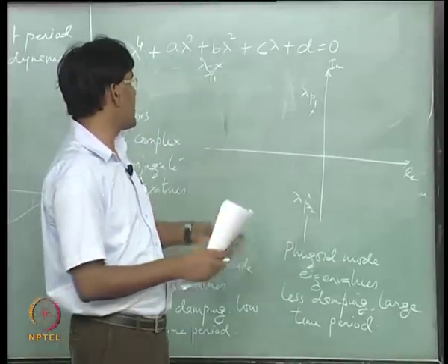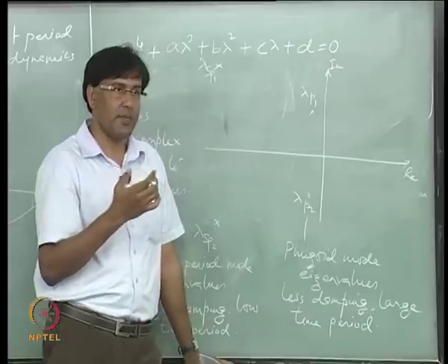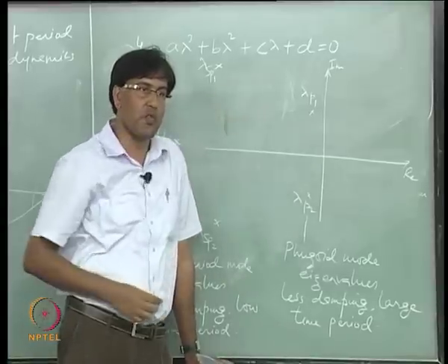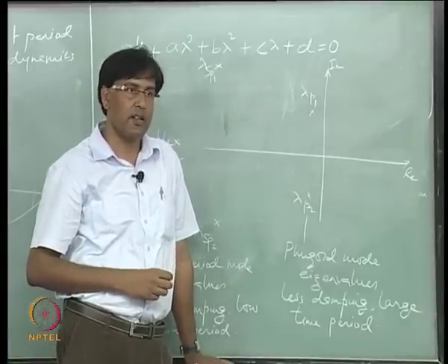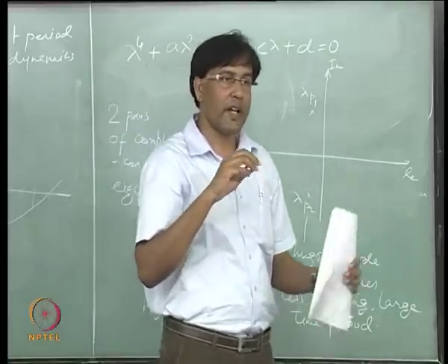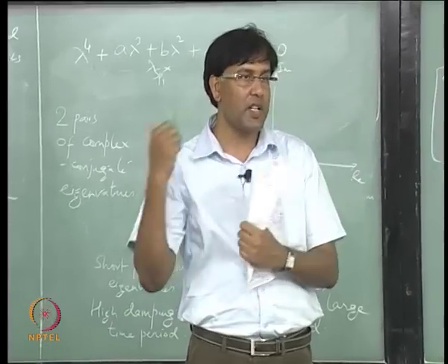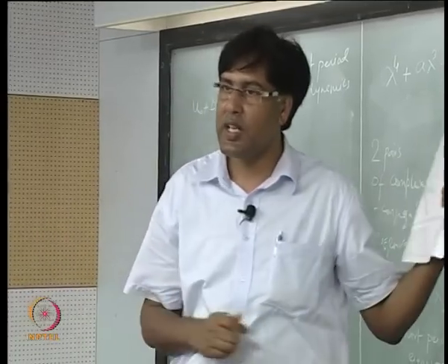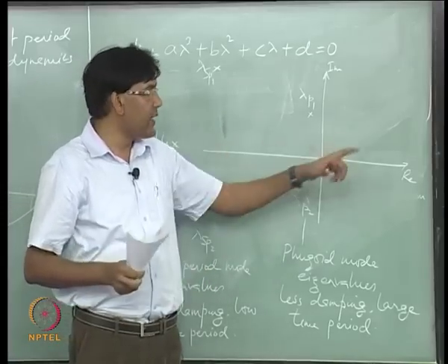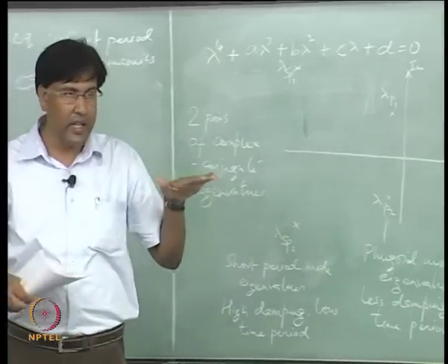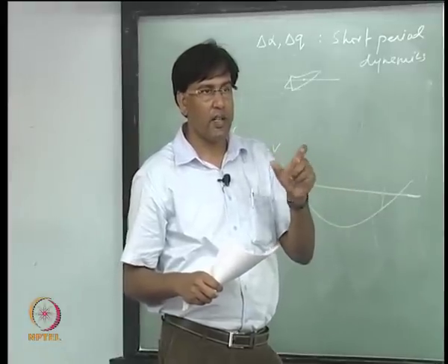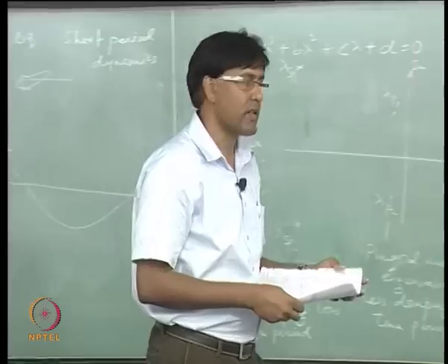There are all kinds of things possible when you change aircraft parameters, because these eigenvalues depend upon parameters. When you change the parameters, these eigenvalues are going to move in the complex plane. But at low alpha flying condition, where we can relate our aircraft dynamics with some of the design parameters, that is what is our interest right now. So we are flying a condition which is alpha equal to 0 right now. We only have forward speed and theta naught which is not equal to 0.